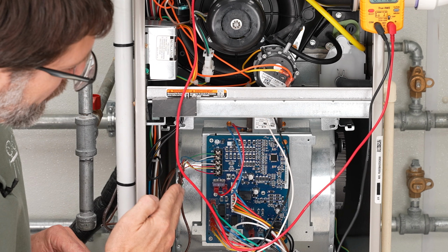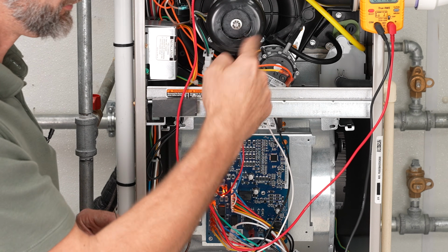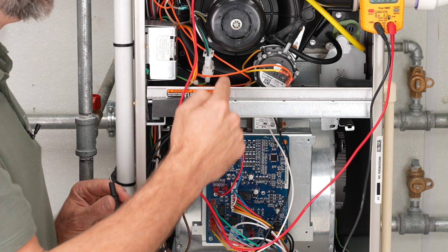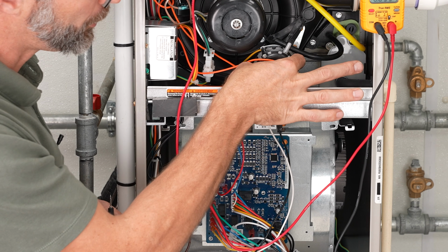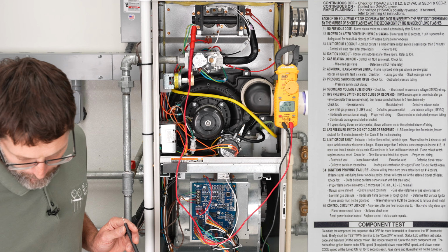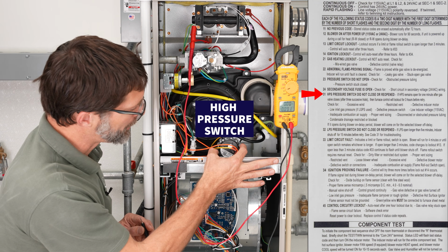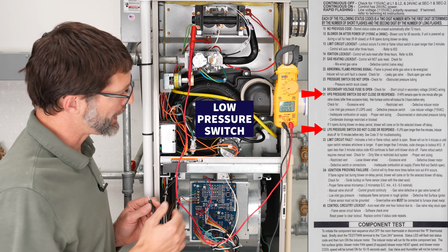So right now we have a call for heat, we've got 24 volts on the W, this inducer motor should be running right now. And if it were running, then this pressure switch should close. So both of them should close, the one in the back and the one in the front. And so in this case, number 31 has to do with this high pressure switch, 32 has to do with the low pressure switch in the back.